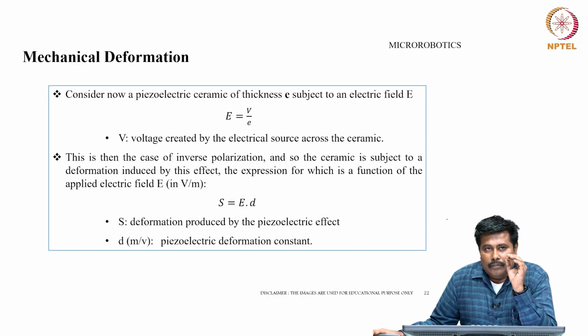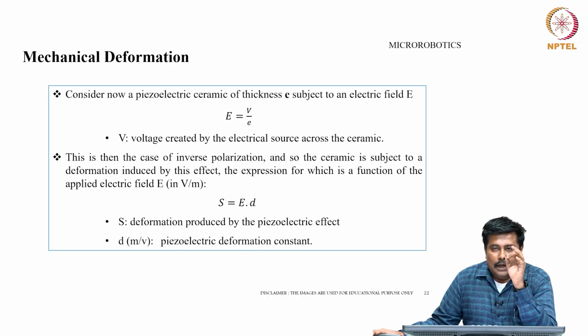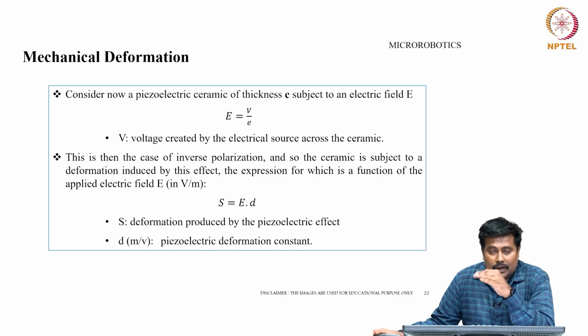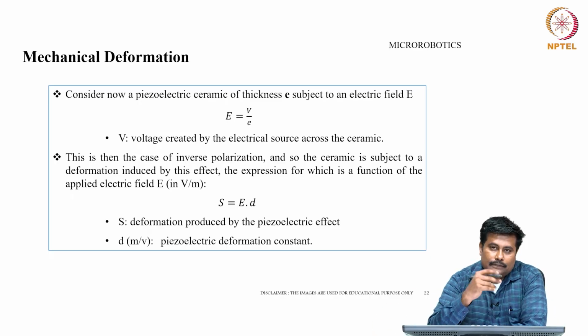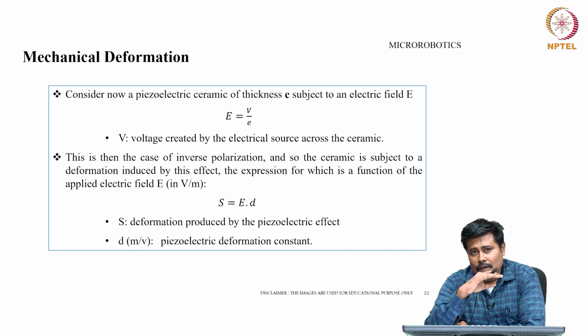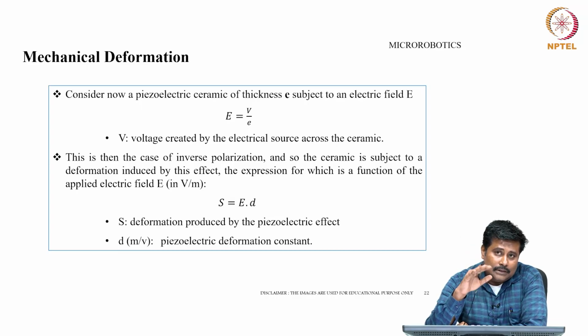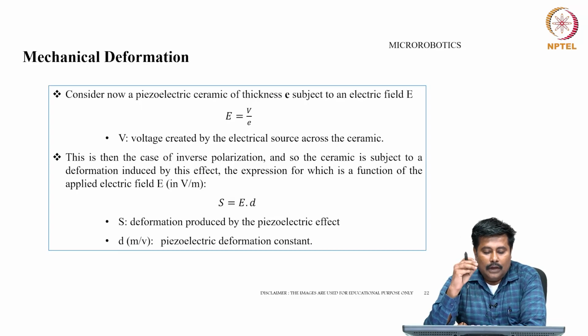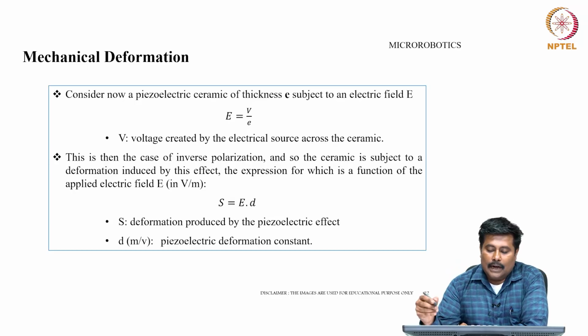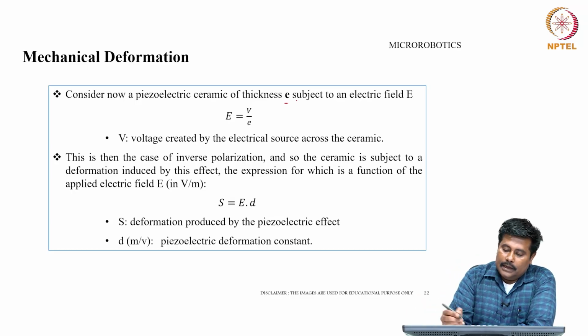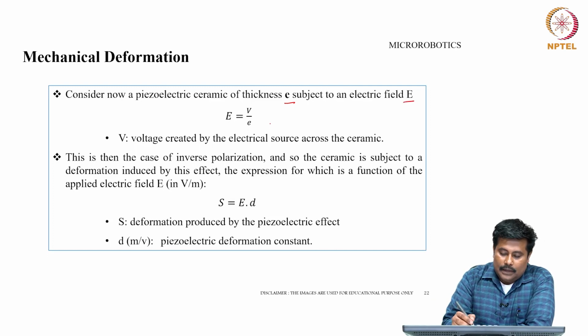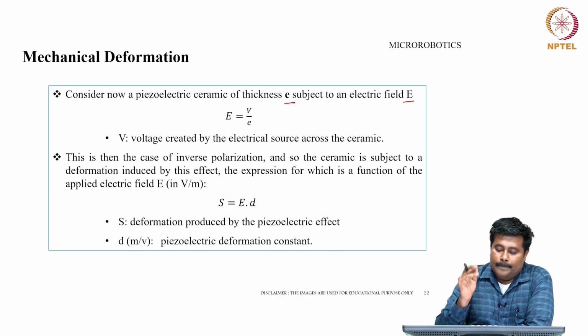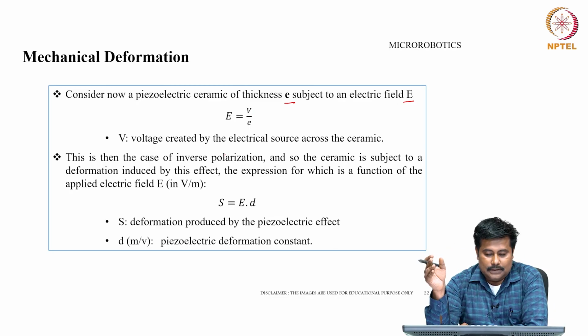Now, let us see some fundamentals of these piezoelectric actuators or piezoelectricity. As far as piezoelectric actuators are concerned, piezoelectric ceramics are being efficiently used. Consider a piezoelectric ceramic of thickness e subjected to an electric field capital E. The electric field E equals V by e, where V is the voltage created by the electrical source across the ceramic and e is the thickness.